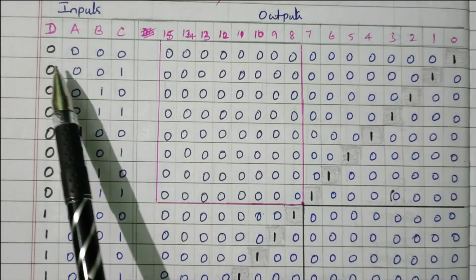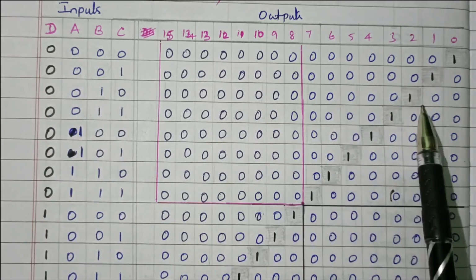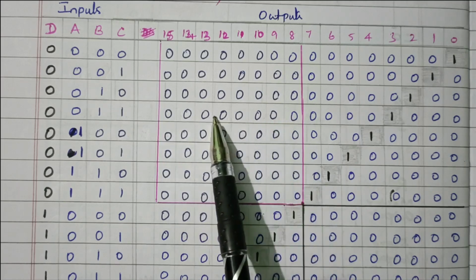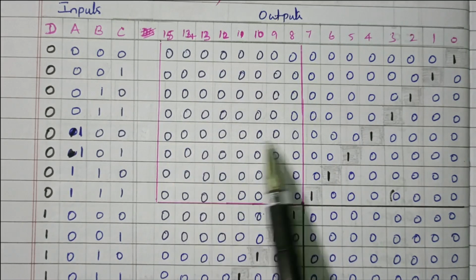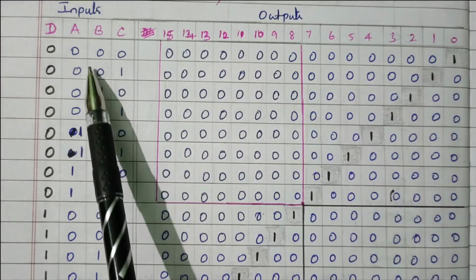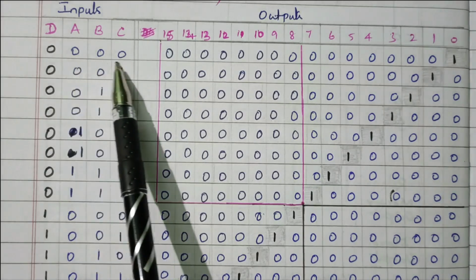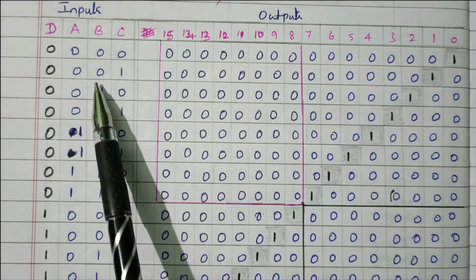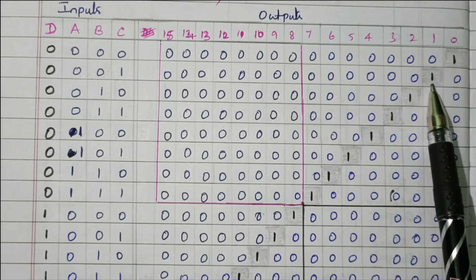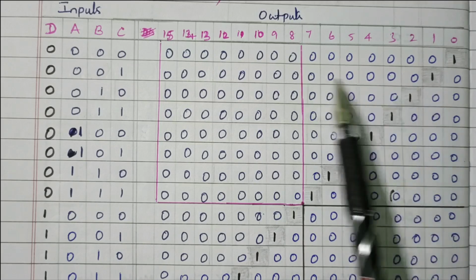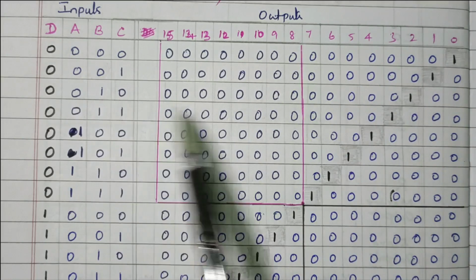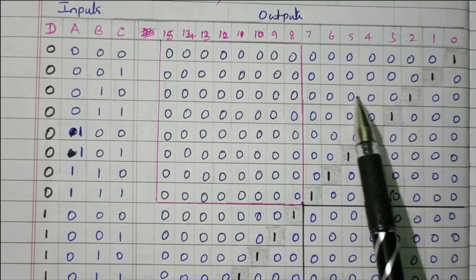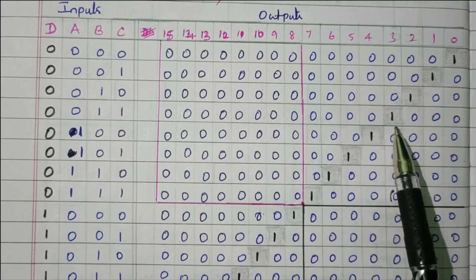We will see how we are getting them. So D equal to 0, top decoder is enabled, bottom decoder is disabled. So the output of the bottom decoder, all the outputs from 8 to 15, is 0. Now we'll see how we get the 8 different outputs from the value of ABC. 0, 0, 0 means D0 will be 1. Other digits are 0. 0, 0, 1 means D1 output is 1. Other digits are 0. 0, 1, 0 means D2 output will be 1. Other digits are 0. 0, 1, 1 means D3 will be 1.